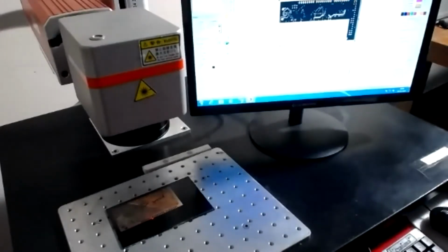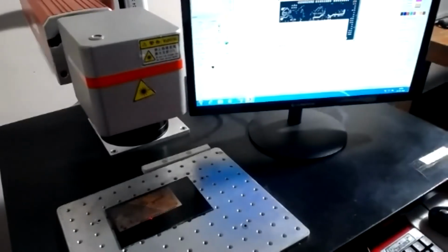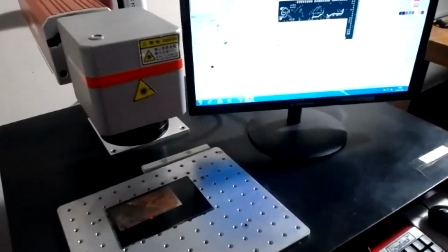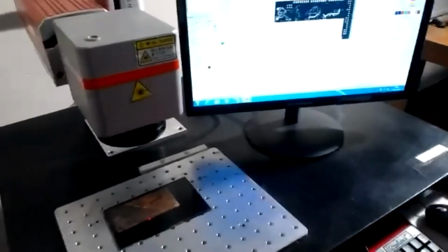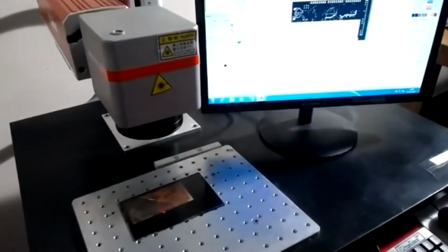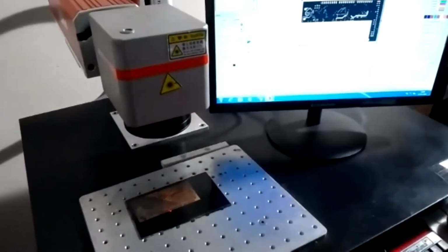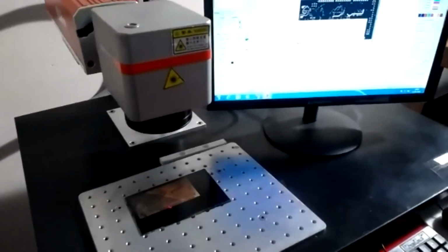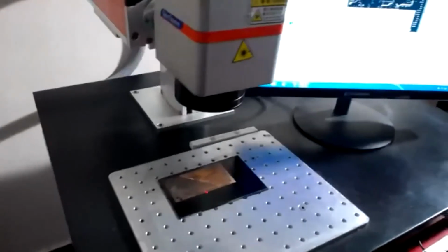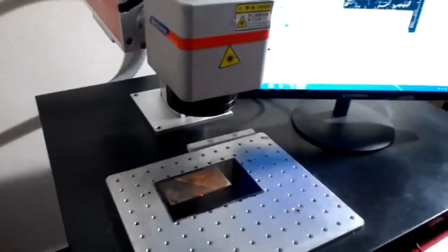So one of the advantages is that the output comes very fast. You can make it ready in a very short time. So altogether, I think this process will take 3 hours to make one PCB. The time consumption will be limited to the laser area and the etching area, because etching you can manage with more trays, and UV exposure also we can do, but the limiting area is basically the laser.